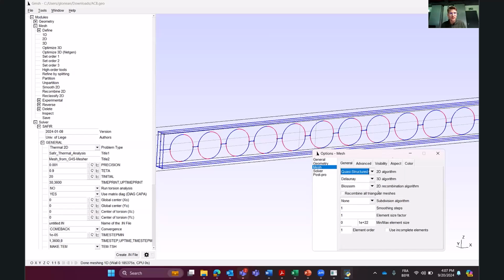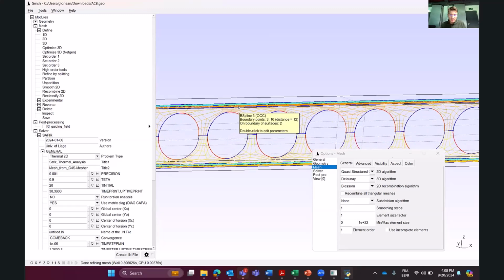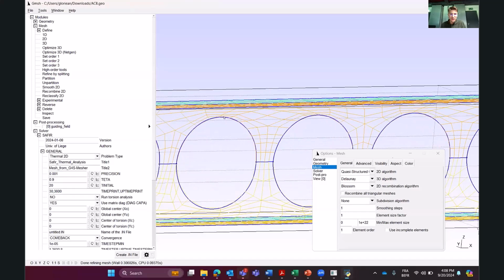I guess it's because it's not yet fully validated. But now if I press the 2D mesh again, I would get, if it works, directly squared elements. And by directly refining, by splitting, I get a mesh which looks cleaner and works a bit better, but still we do not like so much those slender parts in the top T here.